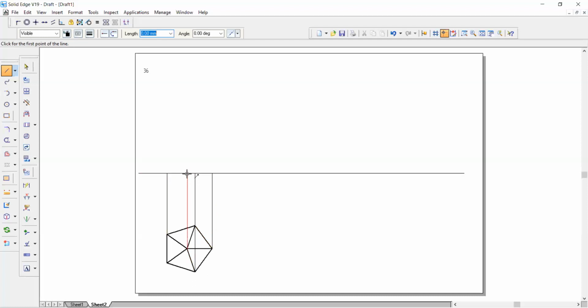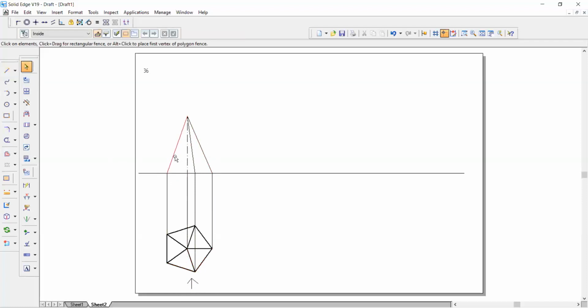And we know that you must always project the axis line first. So in pyramids, this axis line is given as 50 mm. Just enter 50 as the axis line. Only after you draw the axis line, then you join these lines here. So join this line totally. Then you join this. And you also have to join from here, because this is also one of the edges. So when you are seeing this in the front view, from here, this edge and this edge will be visible. So these three edges are visible edges. And the rest will be overlapping on each other.